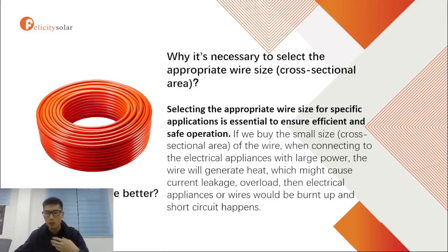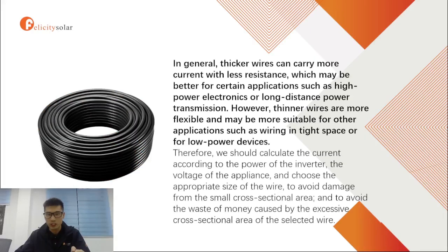But what if we use a bigger one? Is a bigger gauge wire better? Actually, no. It depends on what we need. In general, thicker wires can carry more current with less resistance, which may be better for certain applications such as higher power electronics or long-distance power transmission. However, thinner wires are more flexible and may be more suitable for other applications such as wiring in tight spaces or for low-power devices.